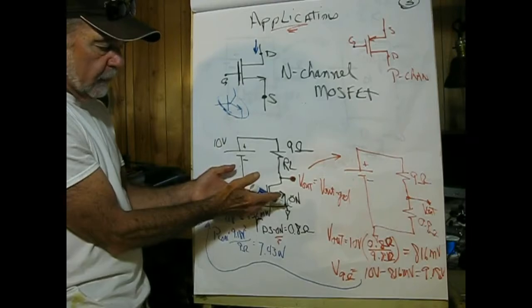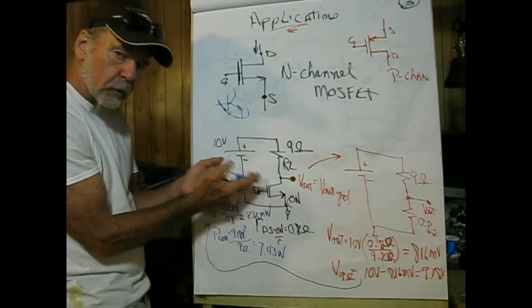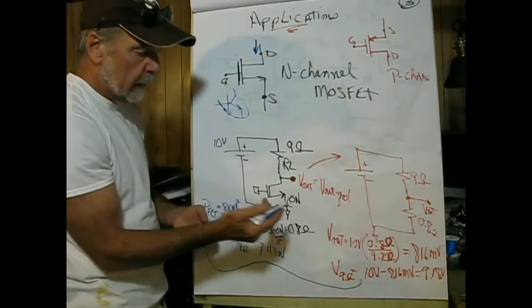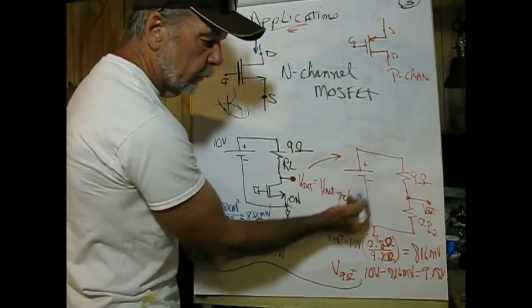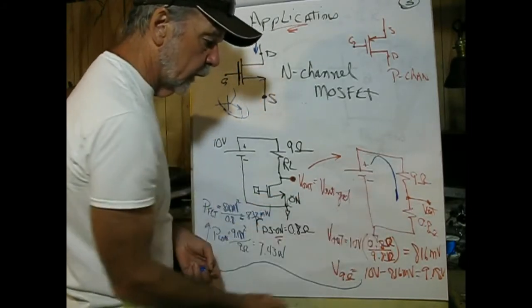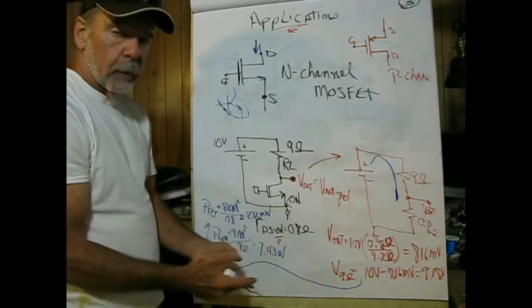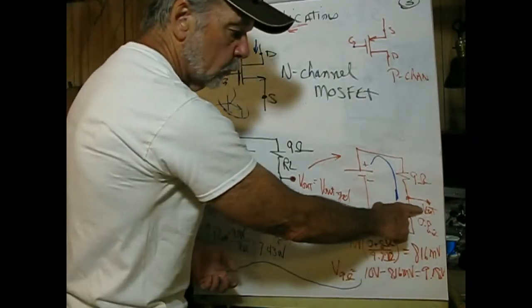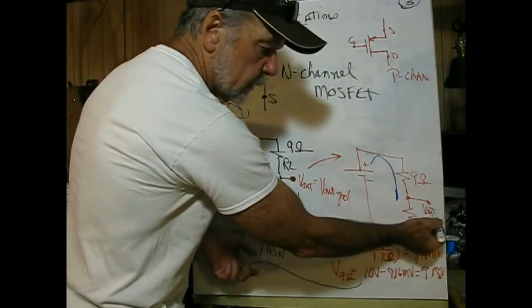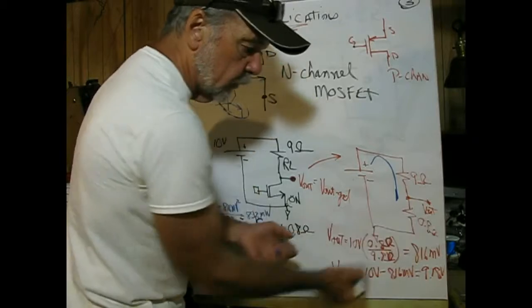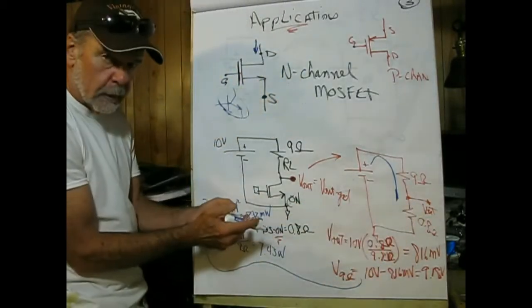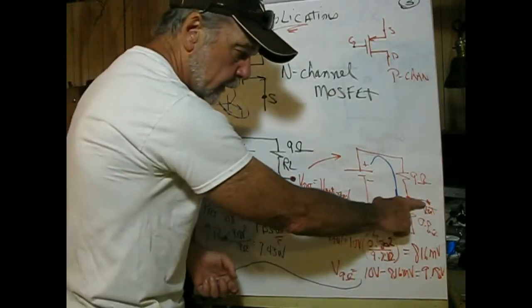So if I'm going to analyze this circuit, which has a 10-volt battery and a 9-volt load, I'm kind of confused by this symbol of the transistor, so I'm going to represent that with its equivalent circuit when it's turned on. As you can see, that breaks down into a very simple voltage divider system, current flowing in this direction. If I want to know V out, remembering that this is a doubly subscripted variable, the second subscript is ground in this case, so the black lead of your meter will go here, and the red lead for V out would be here.